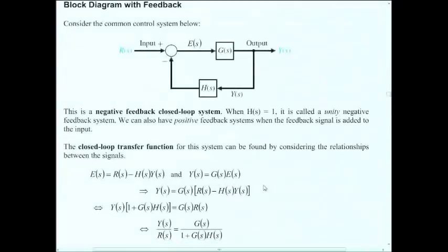So consider a block diagram that has some feedback, really basic feedback, where you have an input signal, you have this feedback signal, they are combined by the summing junction to get a result, which then passes into this forward transfer function in the forward path, so from left to right, to give rise to the output. But the output is being fed back, multiplied by some transfer function to give rise to this feedback signal. And I'm interested in finding the ratio y over r, the total transfer function, given the transfer functions of the blocks within the paths.